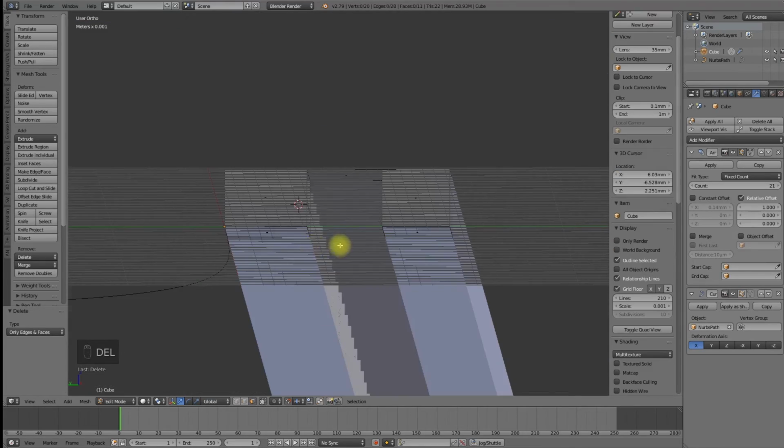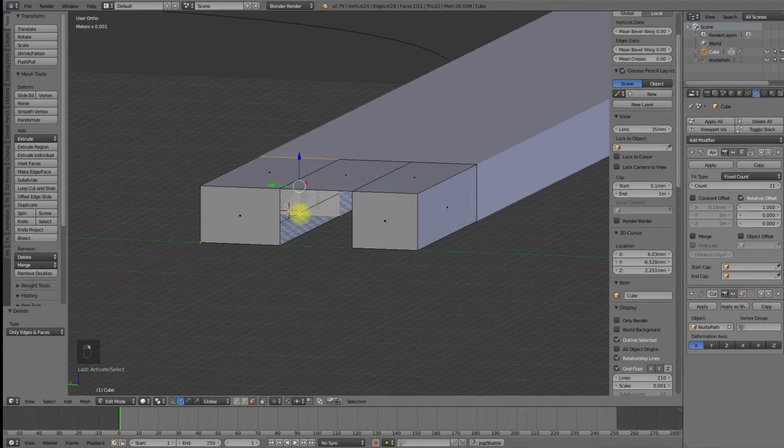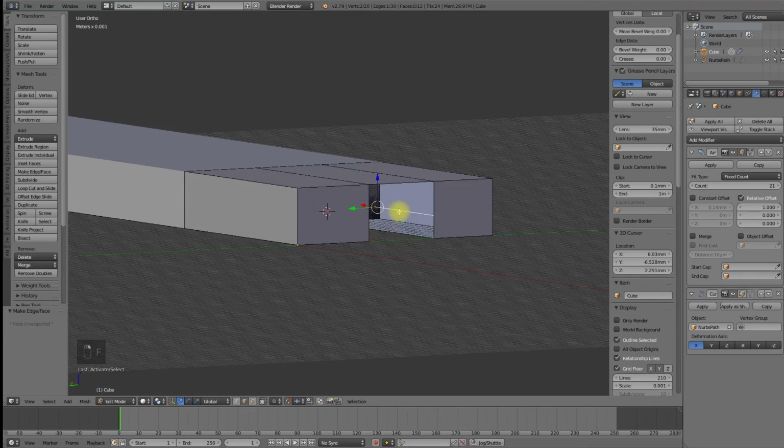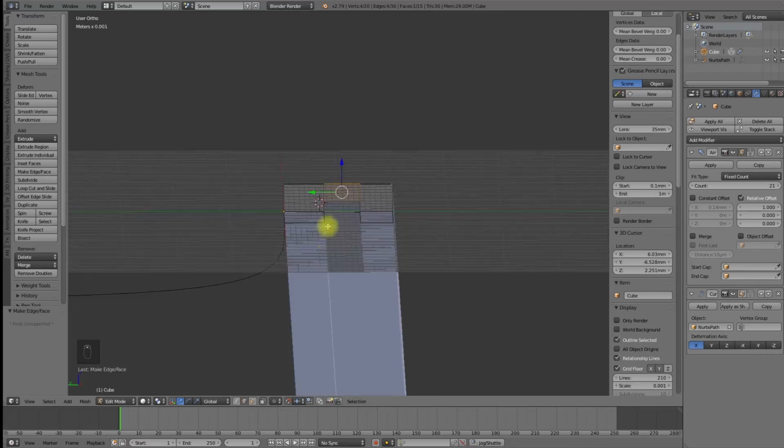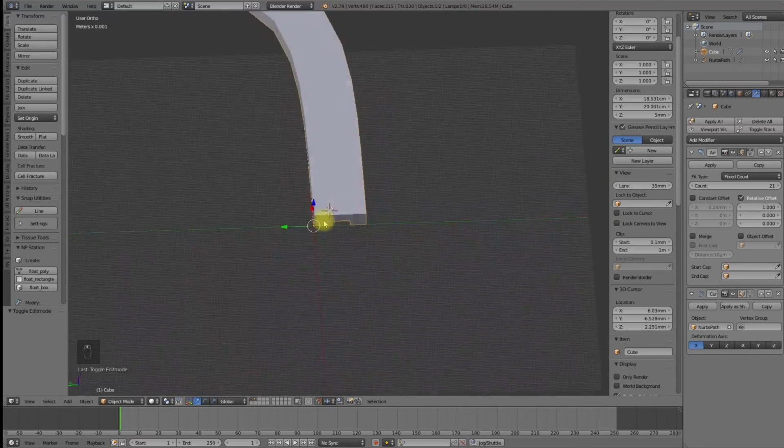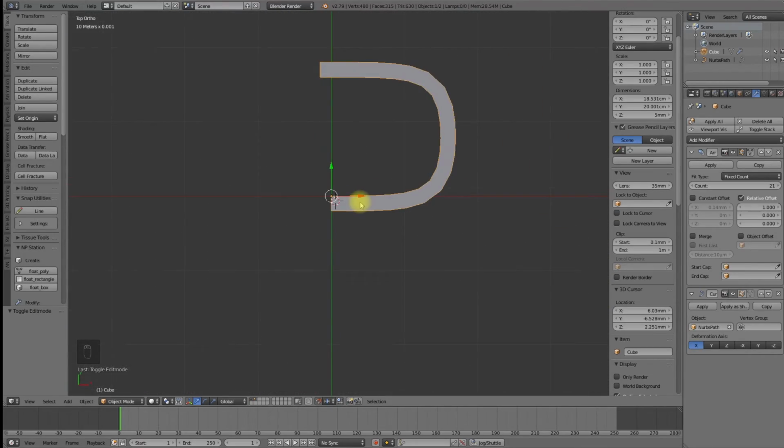Modify the shape object to define your profile. After the modeling of the shape object, I set the length of the shape object to 2 mm, to have a smooth result and to define the overall length with more precision.